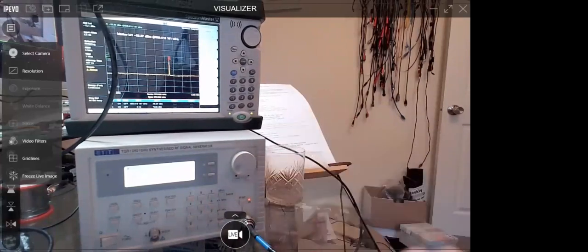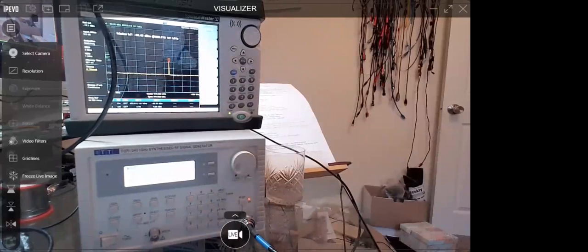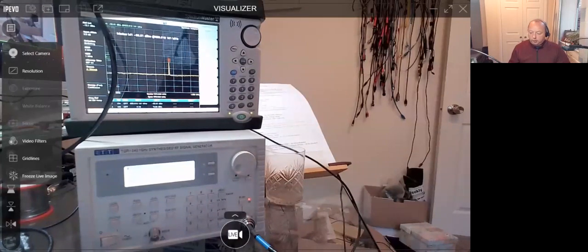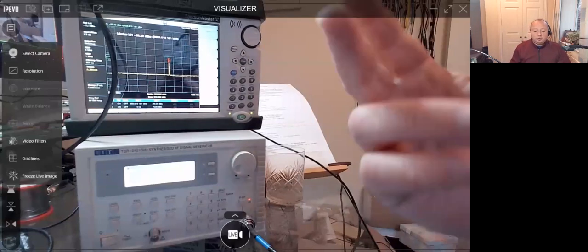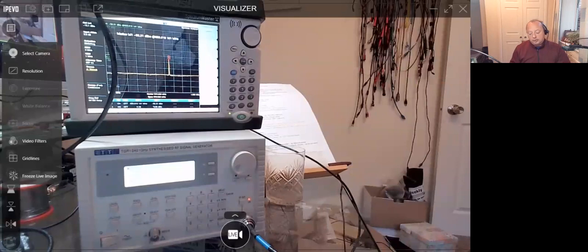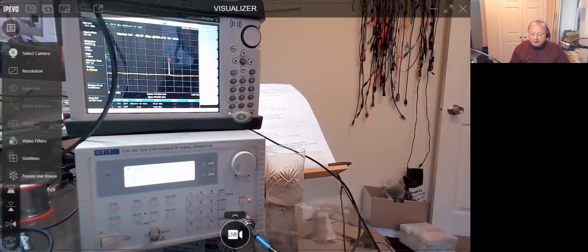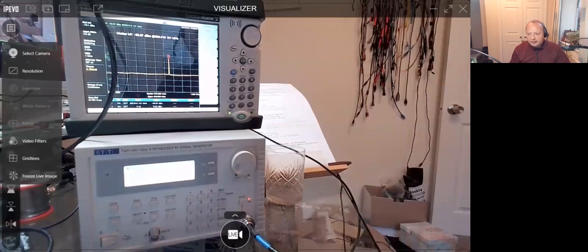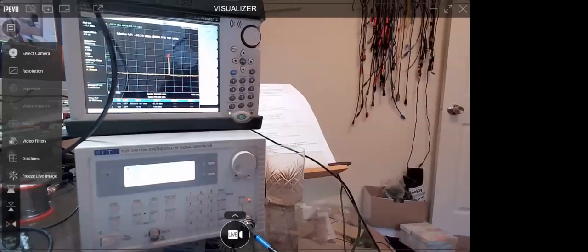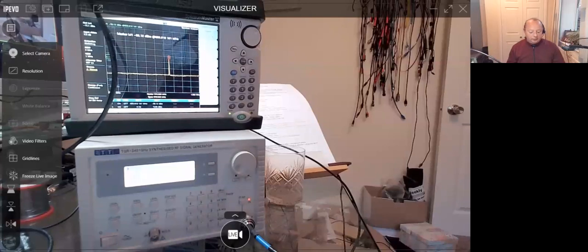But yeah, I was going to say maybe you could just put some capacitors in, and if it starts working, then you know you've fixed it, even if you don't know why. Well, that's very true, because you've got to know that you've got a problem. Yeah, you could absolutely guess, which is not a bad solution. But where do you put the capacitors? How do you fix it? There's the other question. Being able to inject the right frequency gives you the confidence that the solution has fixed the problem. Well, how did knowing the frequency help you to know where to put your capacitors? Okay, so sizing them. Right.